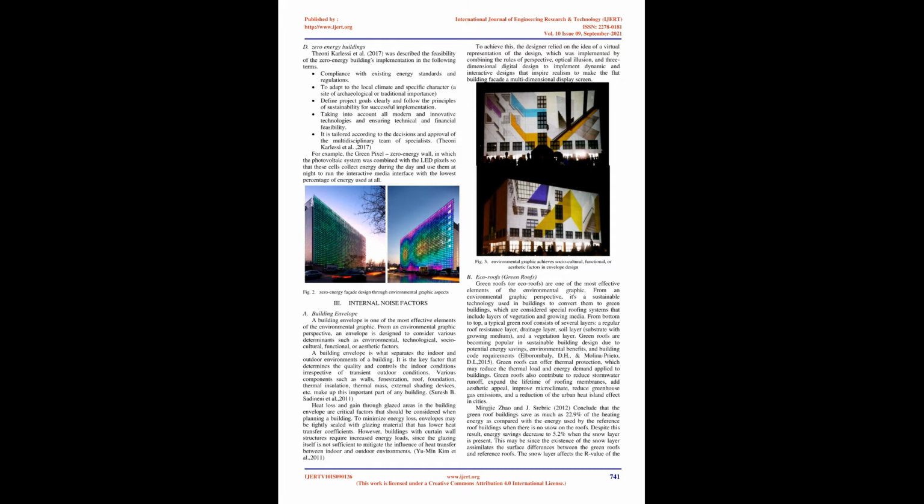Solar energy entering a building through opaque metal facades is quantitatively analyzed by excluding the influence of outdoor air temperature on the building's net heat gain. The solar energy entering a building through an opaque metal facade is of the same importance as the solar energy entering the building through a window to reduce building heating energy consumption. So, the full use of solar energy to make users satisfied from an environmental and economical view can be achieved by a significant reduction in building heating energy consumption that can be achieved by appropriate building metal facades design.